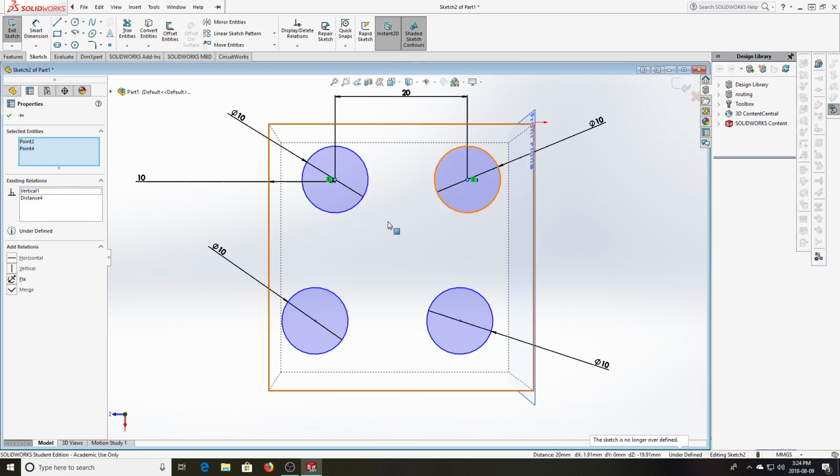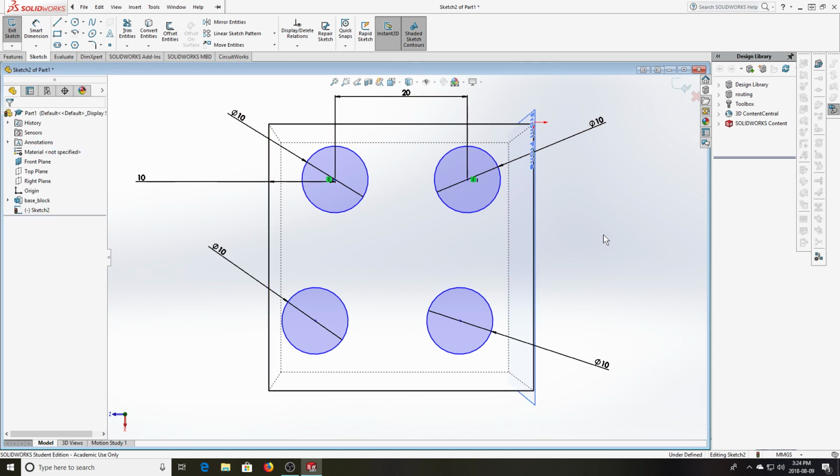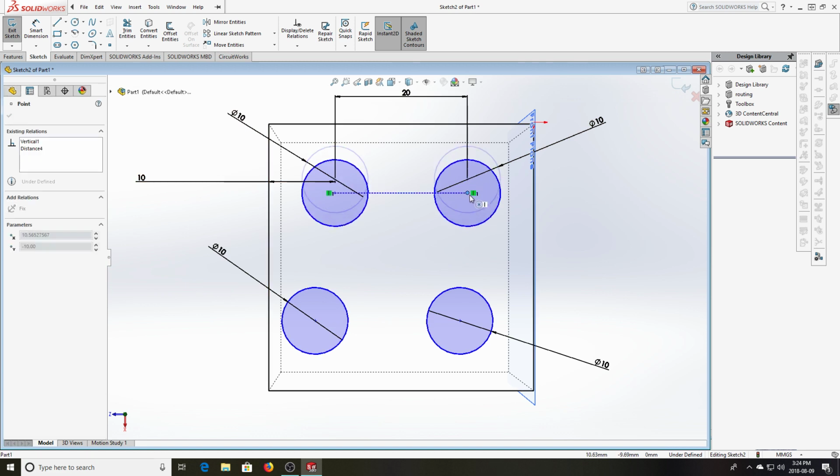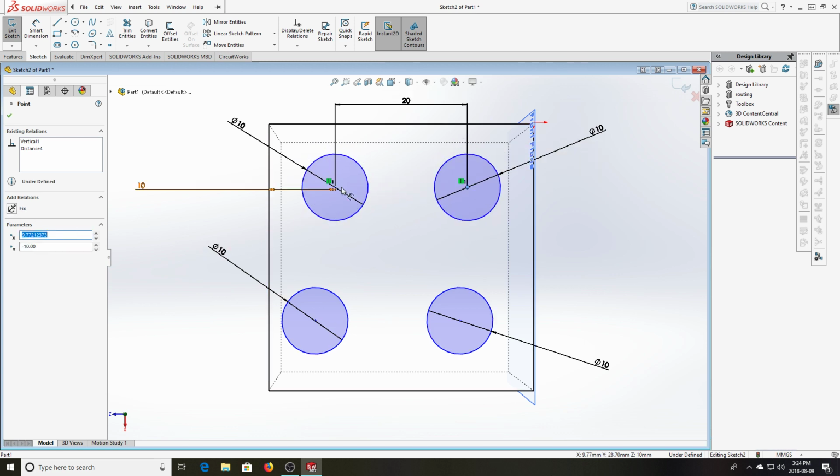And when I do that, you can see that this circle and this circle are now in the same line as each other. So now whenever I try to move any of these parts, these guys stay together. I'm trying to move it sideways, let's say, and it's giving me an X and it says it can't do that, and moving it up and down it can do. The fact that I can move it up and down kind of indicates that I haven't fully defined what this part is supposed to be like.